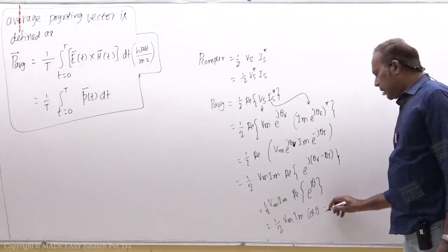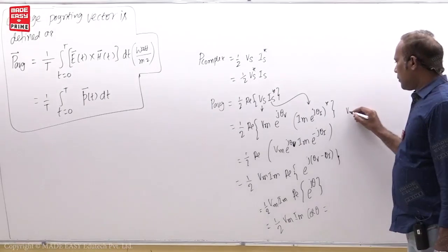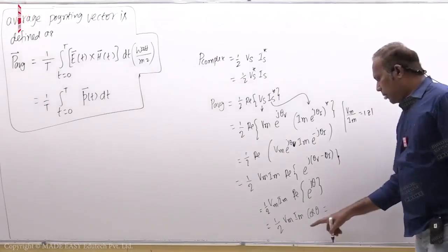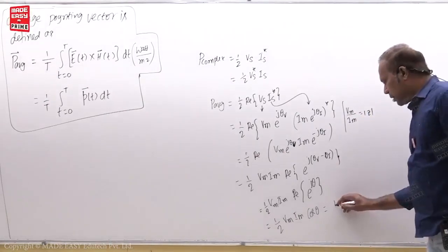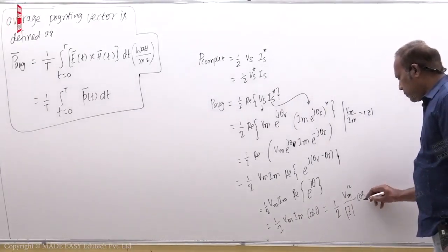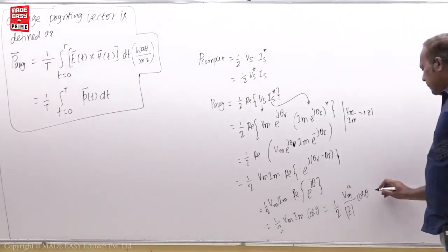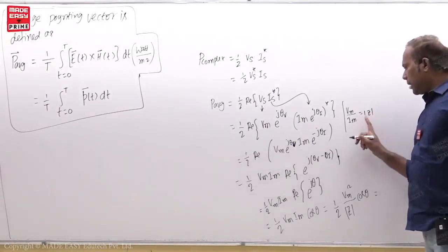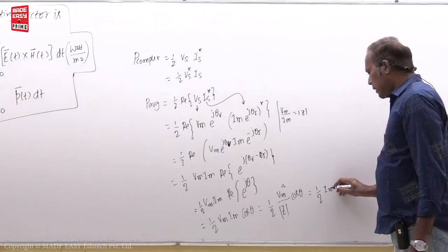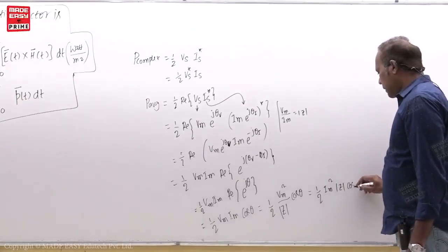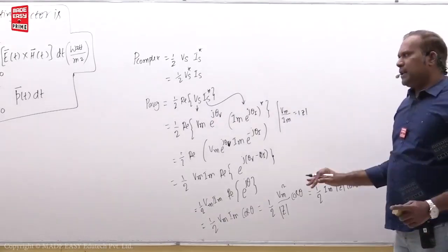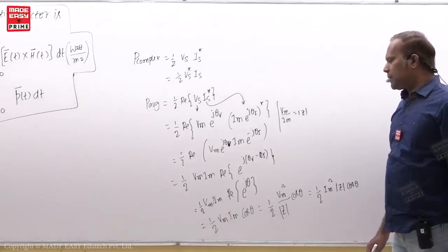If you want to convert only in terms of voltage, then Vm by Im is equal to modulus of impedance, dear students. Now in place of Im you put Vm by mod z, then you get half into Vm square divided by mod z into cos theta. Similarly, if you write Vm is equal to Im into mod z here, then you get half into Im square mod z, then cos theta you get. So in this way, similar to this, we get power equations in our subject also.